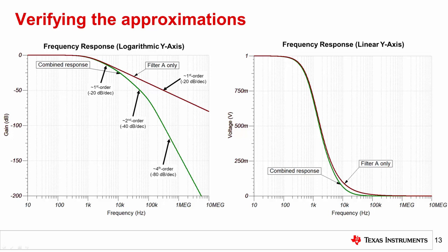Ultimately, these results prove that you can use the frequency response approximations and methods employed in this presentation to quickly and confidently analyze the noise of your next signal chain. You are also prepared to use simulation techniques to confirm the validity of these hand calculations, as well as account for any non-idealities similar to the ones seen with the second-order low-pass active filter.